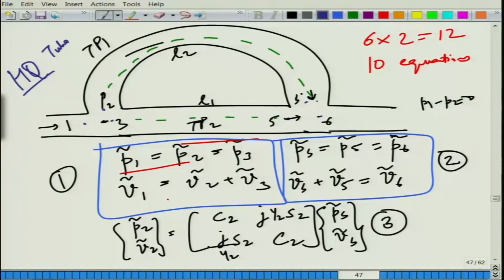So, in the next lecture, that is lecture 2 of week 10, we are going to derive the transmission loss for such a tube, which is called an HQ tube, Herschel-Quincke tube. It has a minimum of 2 tubes, and you can have multiple such tubes. Because of the path difference, we have constructive or destructive interference between waves, leading to some non-zero transmission loss. Note that we have a uniform cross section across this tube. In spite of having a uniform cross section, you have non-zero transmission loss in general because of this destructive interference at certain frequencies.